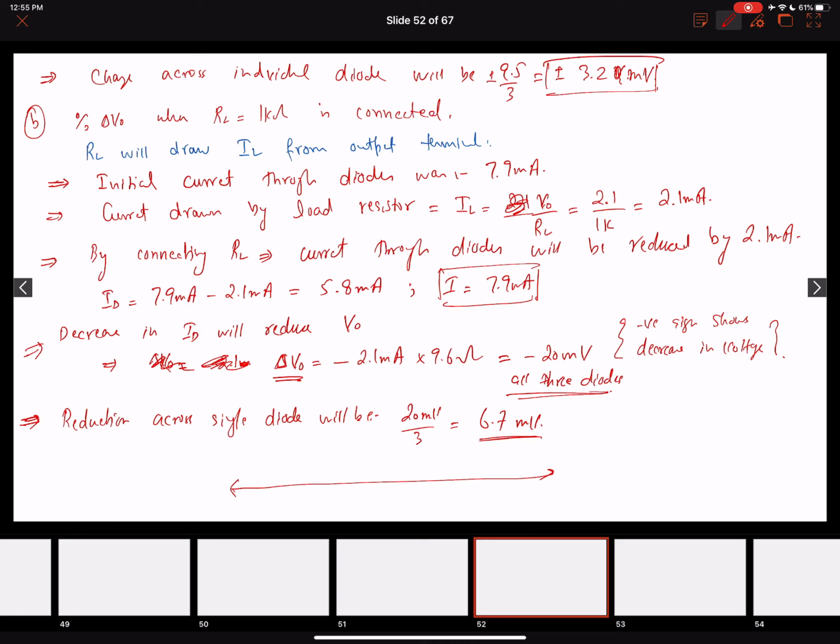So this finishes our lecture. In this lecture we talked about how we can use these diode circuits to develop voltage regulators, in which we are interested in keeping our output voltage constant no matter what. For any variations in the power supply feeding the circuit, or for any variations in the load that will end up drawing more or less current, our output voltage should remain the same. That is the purpose of a voltage regulator.